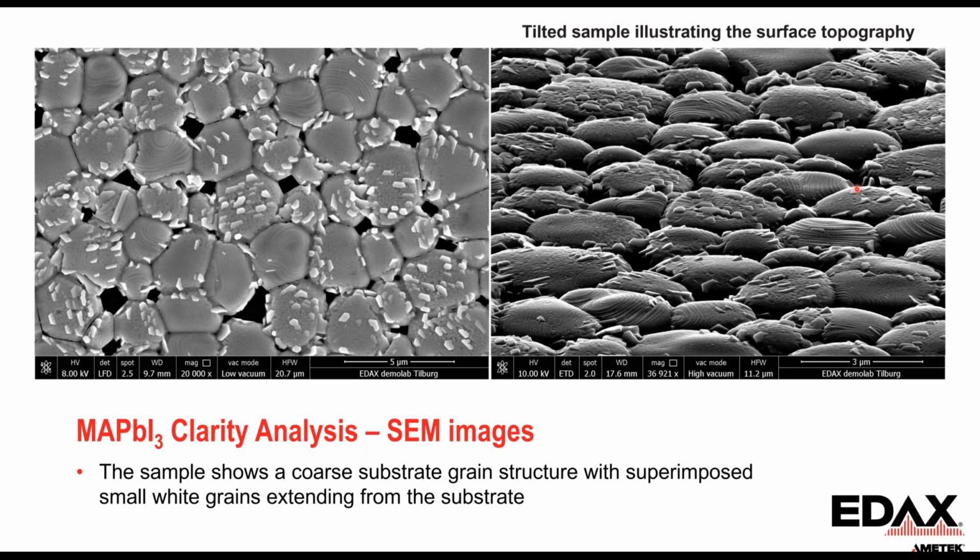So it's not the ideal flat surface we would want for EBSD analysis, and that topography means only certain parts of the image will produce a pattern and produce quality data in a map. That's a function of the topography.